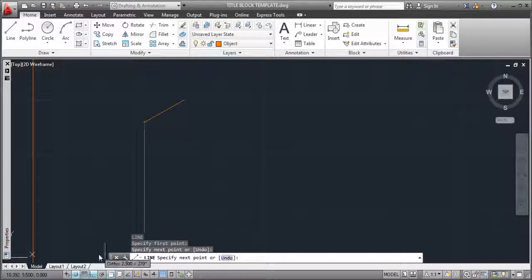I'm going to go ahead and turn off ortho for right now, because with ortho mode off I could just use my snaps and it doesn't matter which orientation the cursor is on, if it's left, right, or top. So I'm going to take it in this direction, 1, 2 snaps, left click, come in this direction, 1, 2 snaps, left click, bring my cursor in this direction, 1, 2, and click again.